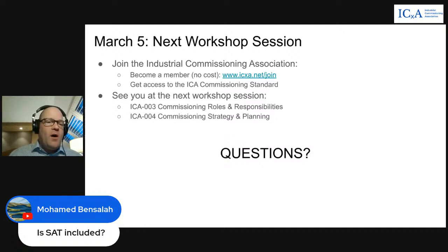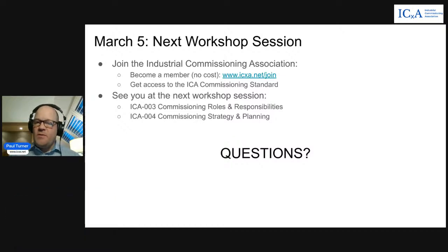Is SAT included? Yep. So site acceptance testing is part of the commissioning process for sure. That would be part of our static commissioning processes. Once we've achieved construction completion, site acceptance testing would be the complement to our factory acceptance testing. Whatever was tested in the factory and whatever results were achieved there, we want to see that that equipment behaves the same on site after shipping, after installation, to ensure that there was no damage. Site acceptance testing is the process to do that.